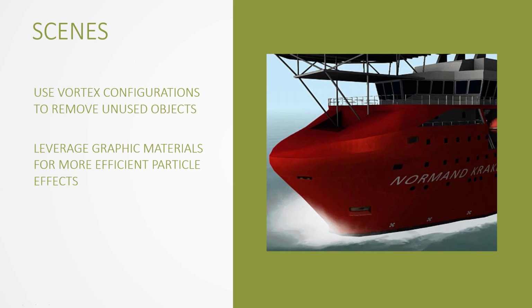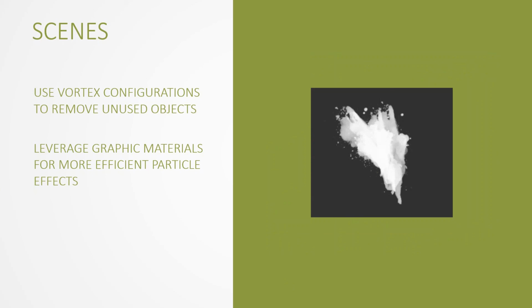So what we're doing instead is that we're replacing each of the little spots of light by a little square that has a texture painted on it. And in this case, the texture looks something like this. So it's a splash of water surrounded by an alpha section. So basically everything that's black is going to be transparent to the computer. So whenever a particle is generated, instead of being just a simple point of light or a pixel, the computer is going to place that graphic inside the simulation and then move it as the particle goes.